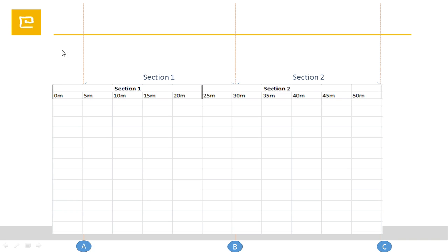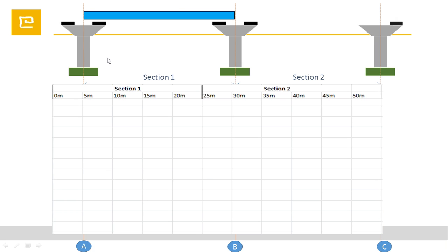So how does it work if it's not TBM and it's an elevated project? We have sections here, and we have a drawing of the elevated metro, like foundation, abutments, and the decking. And you can see that this is a kind of drawing, with the segment and the top of rail here, and the signalization and so on going on.